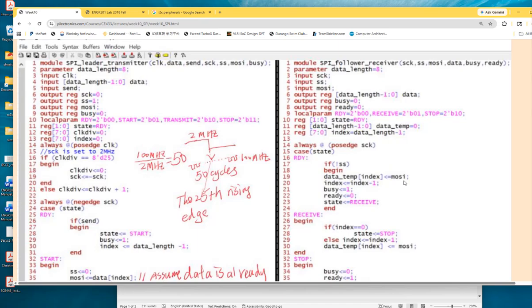So for that one, then you have 20 different combinations of the code, and then we'll send it to a decoder to enable each CS pin individually, right? If you want to send the data to one, then you activate that one only by sending a decoder code first to control the CS. So how does that work on the hardware?